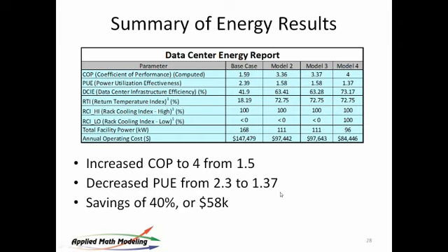Now, you can take these summary reports that I was just showing you and drag them into Excel because we support integration of all of our output with Microsoft Office. I'm showing you this in PowerPoint. You can also create Excel spreadsheets by dragging the summary reports into Excel. I did that for each one of them and then put the cases side by side on that energy chart. So here's our summary. We went from 1.59, or PUE of over 2, down to 1.37. We went from a cost estimate of 147 to 84.